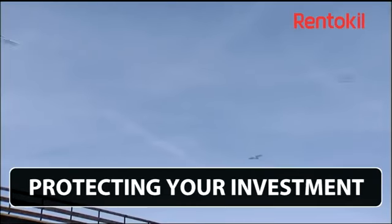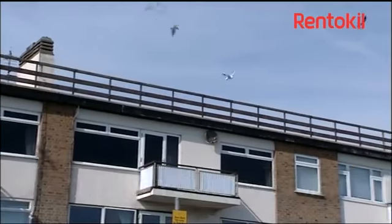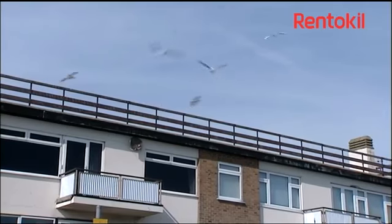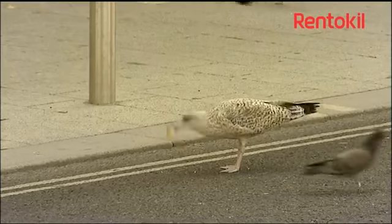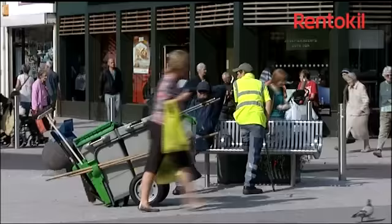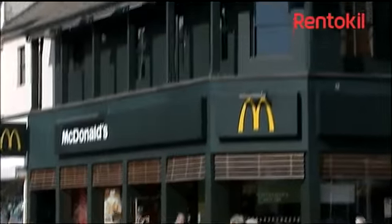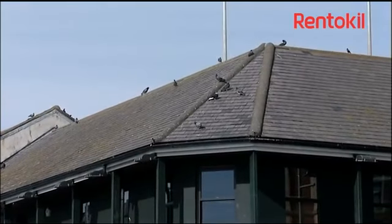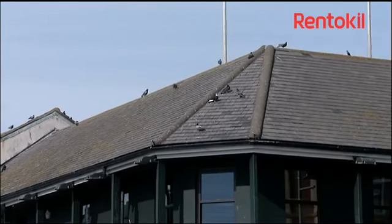The primary requirements for restricting bird activity inside or on a building is good hygiene and bird management. A breeding or feeding site will attract as many birds as can be maintained by the level of food or harbourage offered. Regular cleaning of food debris, covering and regular removal of waste from around and within buildings, preventing birds accessing bin stores or other waste storage areas are all vital elements of restricting bird activity.